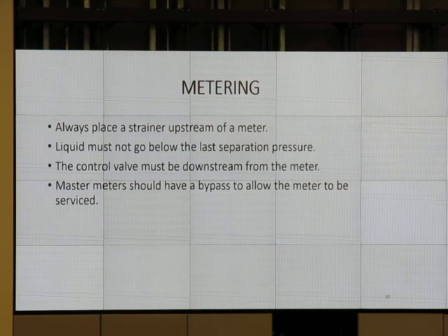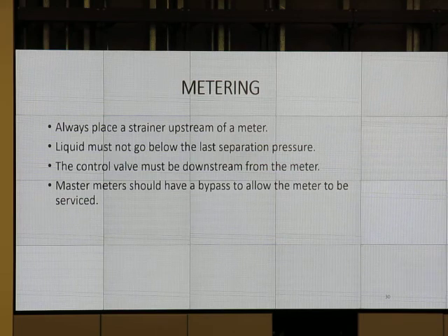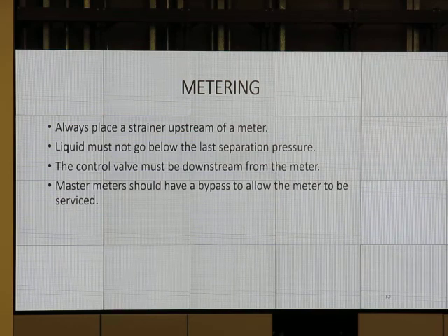So tank, meter, control valve is the ideal way to do it. Or test separator, meter, dump valve. So we keep that gas from breaking out of that meter as we measure it.